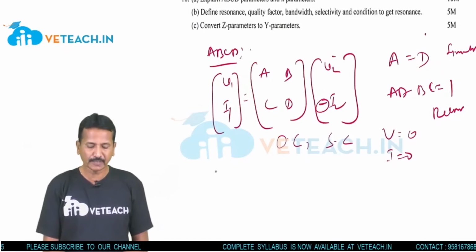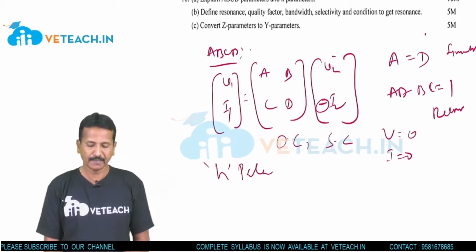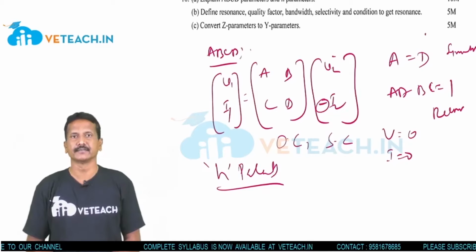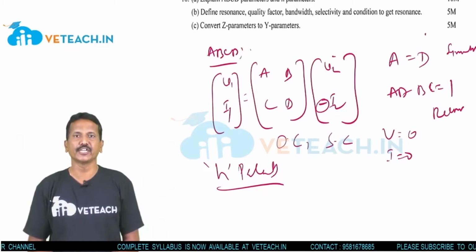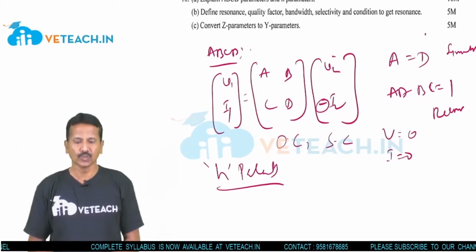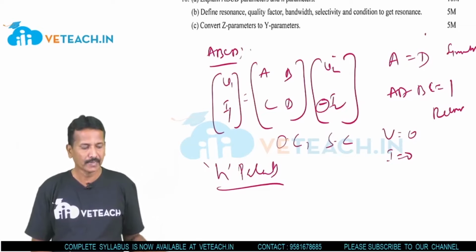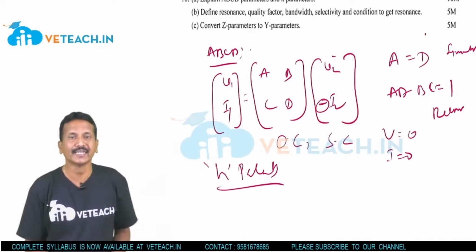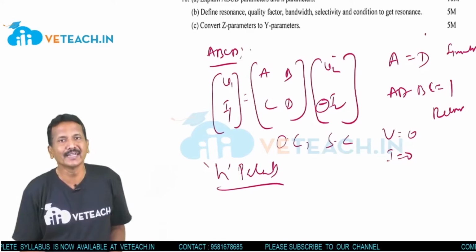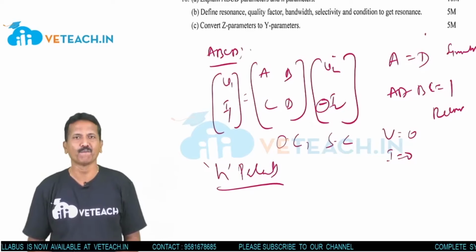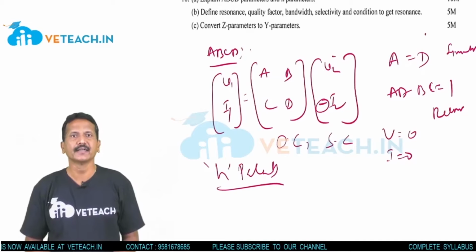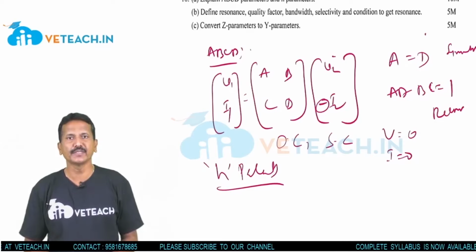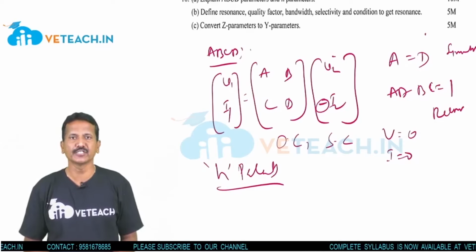In the same way, when we are discussing the H parameters, H parameters are basically used in electronic circuits or equivalent circuit diagrams. So here we have the H parameters H11, H21, H22 and H12 to find. H parameters are used in electronic components, and here also two independent and two dependent values will be there, the relations, as well as symmetry and reciprocity conditions also.